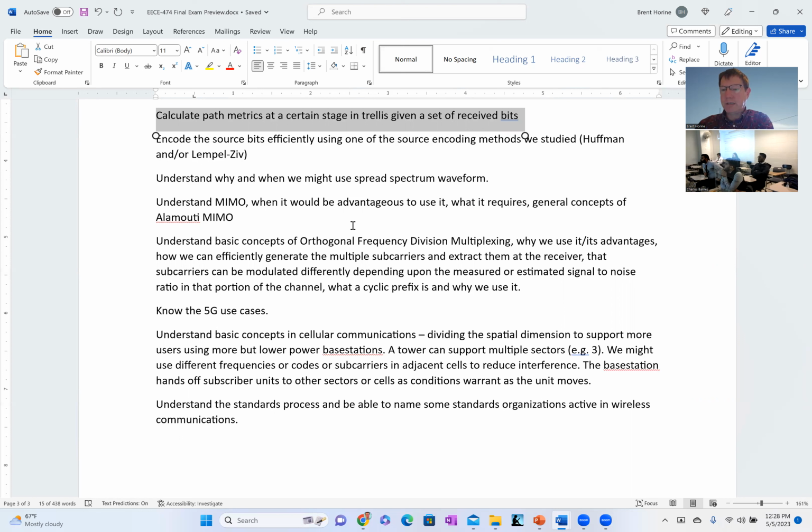And if we just use that bandwidth, and then someone comes along and either intentionally or unintentionally transmits on top of us, then it wipes out our whole signal, right? And we have no margin left to recover anything. Because Shannon says we need a certain amount of bandwidth, and someone's interfering over a significant part of that bandwidth, then we're not going to be able to achieve our communication goals.